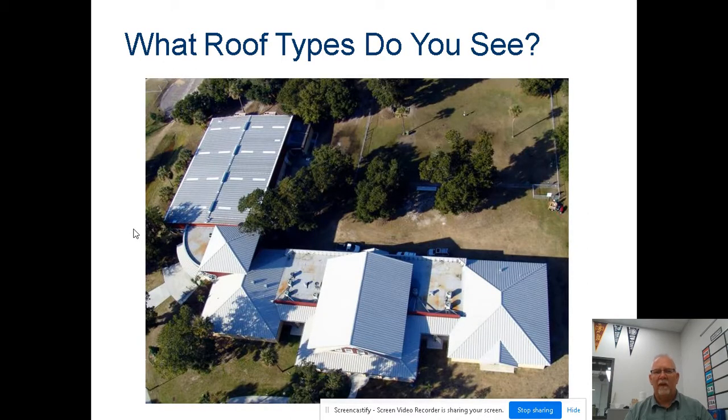Moving on, if we kind of glance at this picture, you can see several examples of roofs. As an aerial view, this may be like a business or a warehouse. You can look here. That is a gable roof. We've got a hip roof in this area. It's like we've got a flat roof here, and another hip in this area because it's got slope on all sides. Another gable roof. This might be a flat roof or a shed roof.